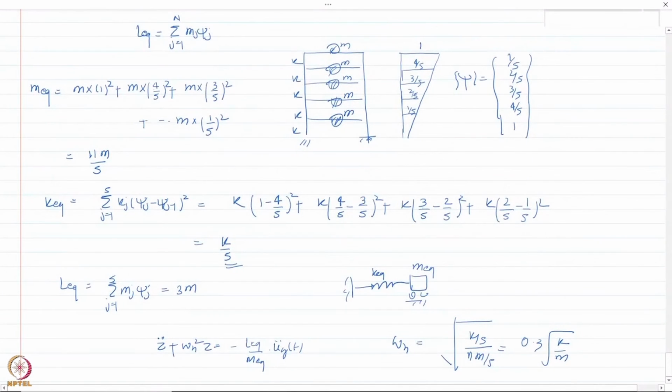So we have seen that we solved a continuous system, and we solved a lumped mass multi-degree of freedom system, a shear type building as well, without having to solve a multi-degree of freedom system. This is the power of a generalized system, by assuming a deflected shape, a shape function or a shape vector for a discretized system.